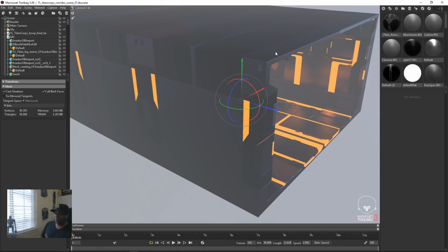But when you send it over to ZBrush or something like that, you need to save the model out, triangulate it. So just keep that in mind when you're exporting any type of object back and forth between ZBrush and Blender. You probably want to get a triangulated OBJ to come back to ZBrush so that you can make sure that your manifold mesh is all closed up with no holes, right?